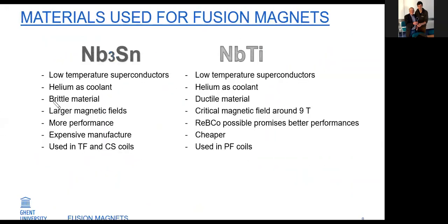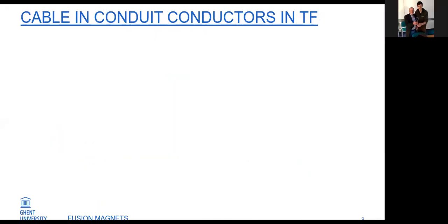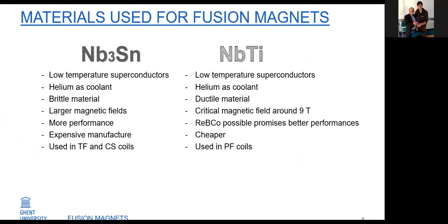Do you have this? Well, what do you mean already? Well, I think all materials have a temperature at which they go from ductile to brittle. I assume that if you say it's brittle and it's a limiting factor, it's going to be brittle over the range of operation, but how high in temperature would you have to go? Because maybe you could manufacture it at a temperature at which it's not brittle, and then it doesn't matter if it's brittle when it's installed.